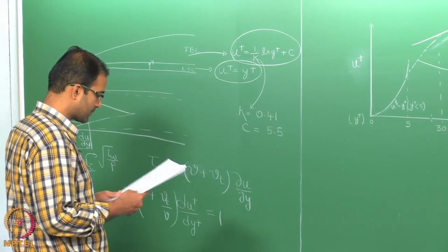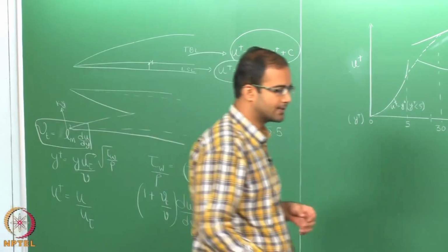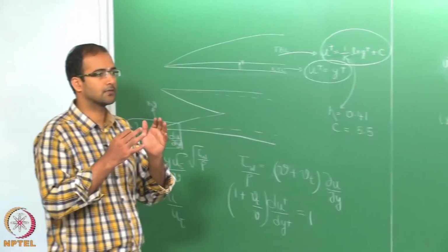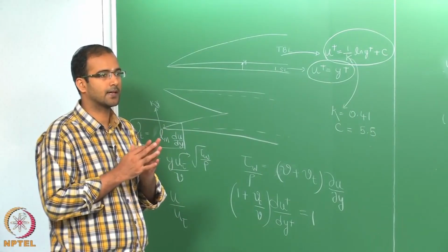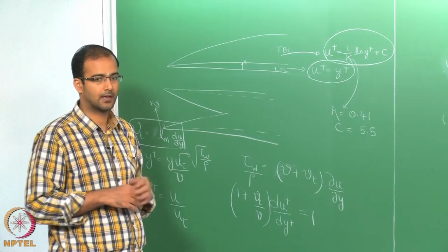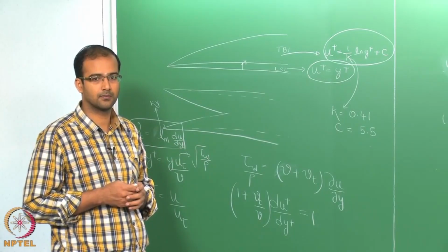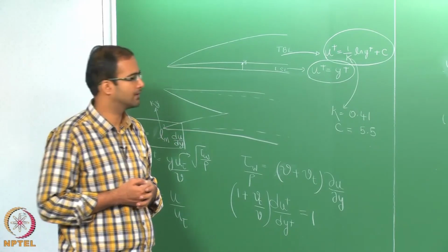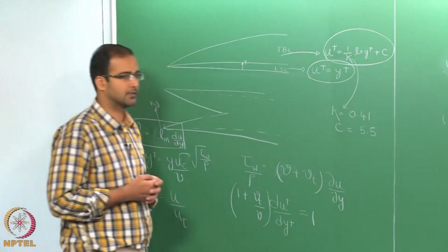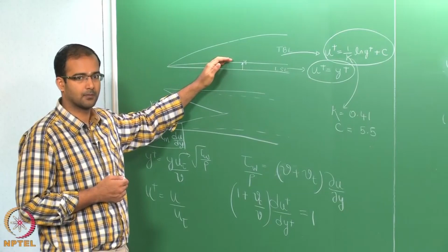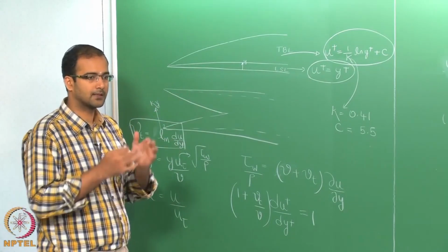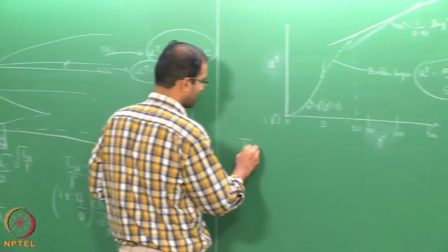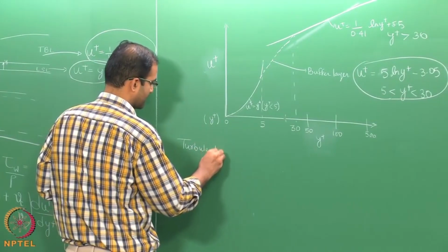Now, one thing I just want to emphasize, from the Reynolds-averaged equations we can again write down the boundary layer equations for turbulent flow, because those RANS equations again are generic Navier-Stokes equations. You can apply that to any kind of flow with pressure gradient, without pressure gradient, with all kinds of diffusion in different directions. But if you want that to be solved specifically for say the flat plate boundary layer, we have to write this in a classical boundary layer form. So, can you try writing down the turbulent boundary layer equations from the RANS equation?